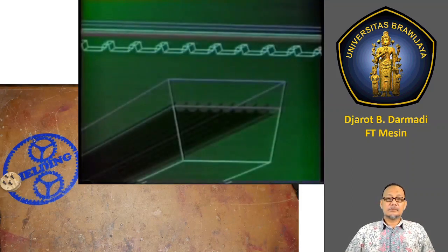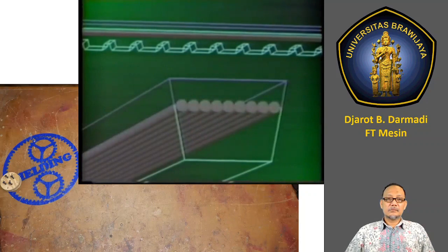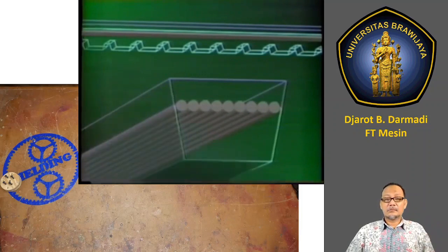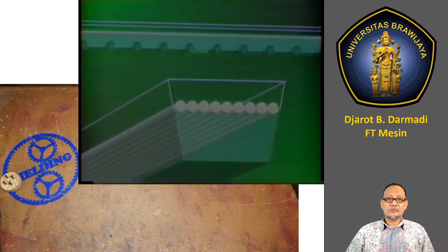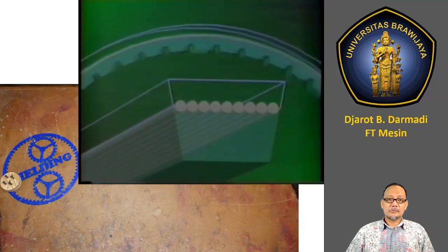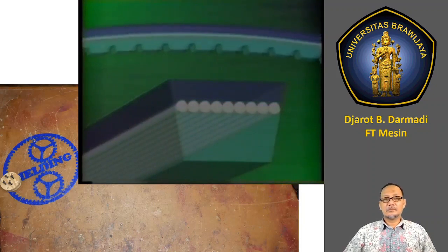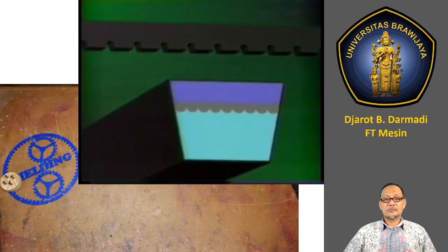A V-belt is designed around two concepts, strength and flexibility. The strength is provided by a row of tensile cords. The cords serve as the load-carrying component and are made of twisted synthetic fiber. The compression section is made of synthetic rubber. It supports the tensile cords evenly and compresses while bending around the sheaves. Conversely, the tension section, located above the cords, is designed to stretch as the belt bends around the sheaves. The cover or top fabric is made of a rubberized fabric designed to provide wear resistance and increase belt flexibility.